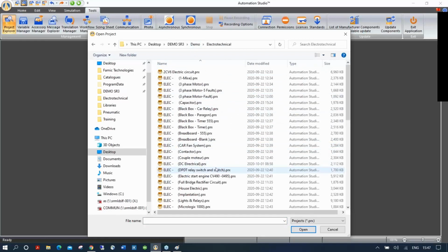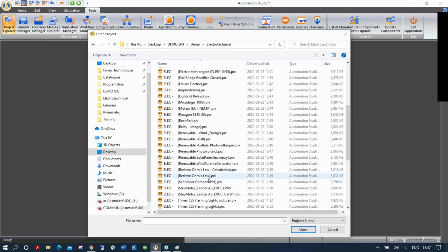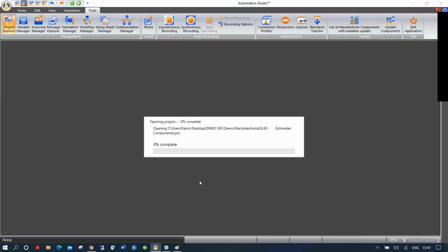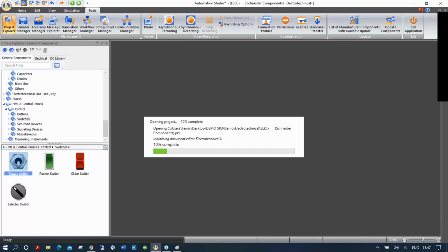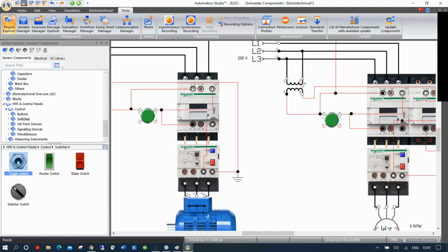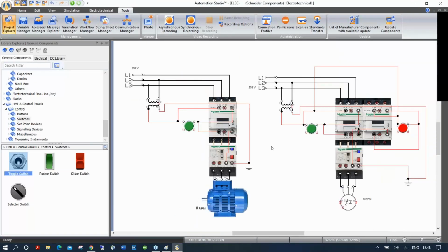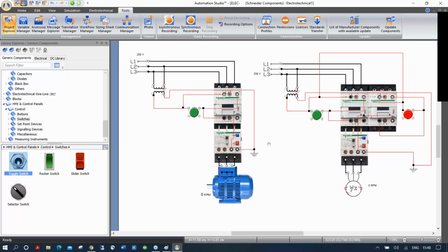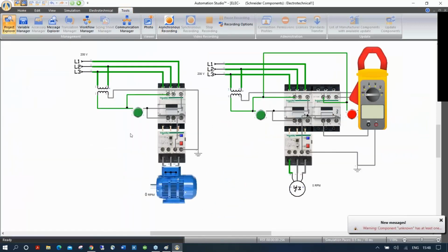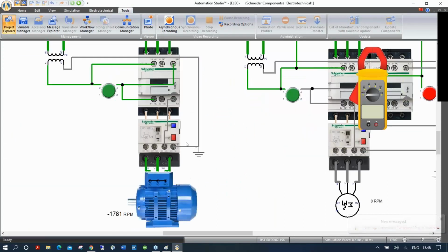We took actual Schneider components, okay, and we've created the custom components for him, and then he can use these components with his students to actually create a wiring diagram, something like this basically. It'll look a lot different than what you do when you use the symbols, but it works the same. If I start simulation, I can engage, the motor spins, I can zoom in a bit, I can stop my overload, reset my overload, and start again.